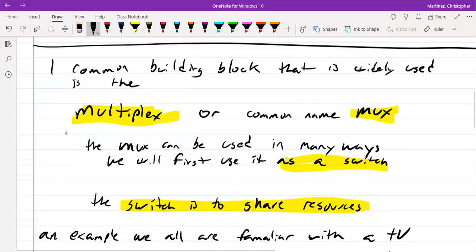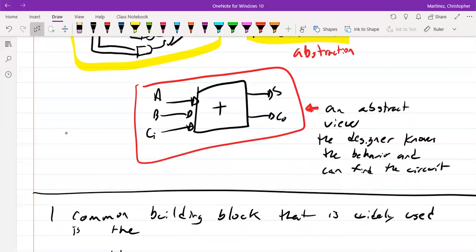Let's just scroll back up real fast. And let's say we have this 1-bit adder. And we know in our circuit, we're going to be doing a lot of addition, but it's all at different points in time. Instead of duplicating this adder 4, 5, 6 times, if it's possible, let's have those 4 or 5 times that we need it all share this one adder.